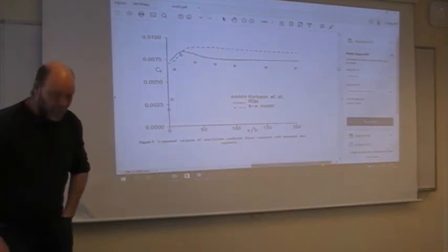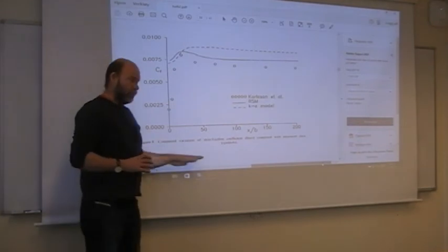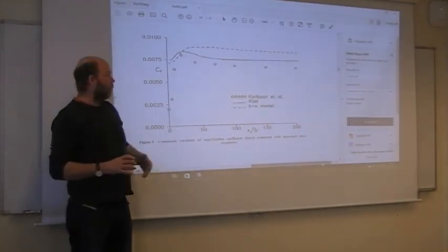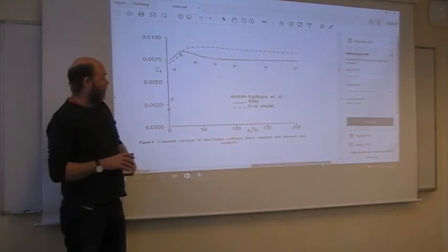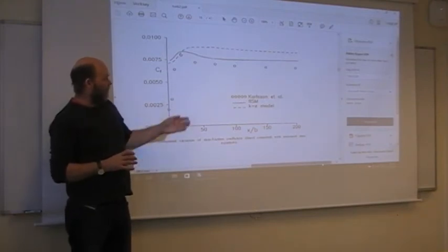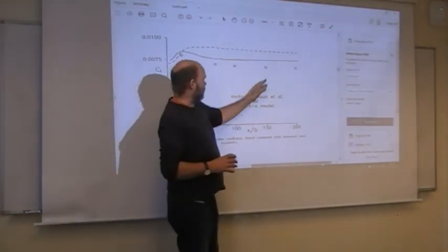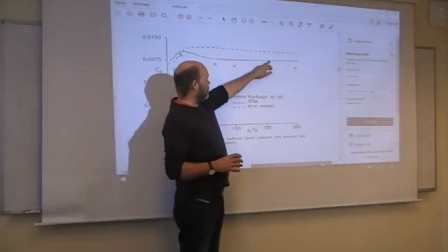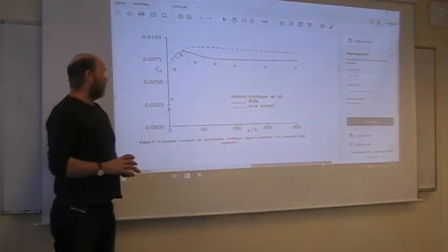And looking at the skin friction, I mean, now we are talking about the frictional force on the lower wall. The changes become quite large. Now the RSM simulation here, well, not perfect with the experiments, but at least much better than the K epsilon model.